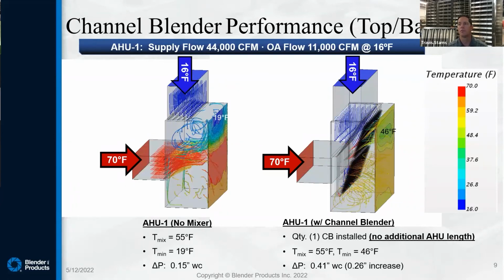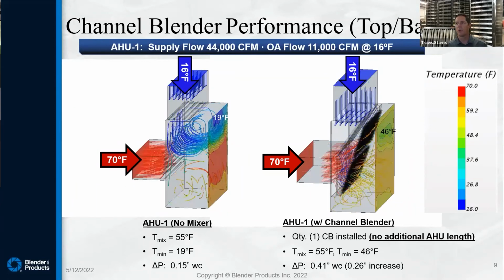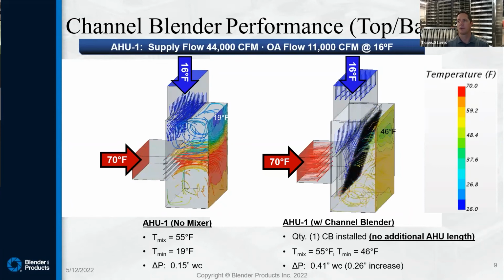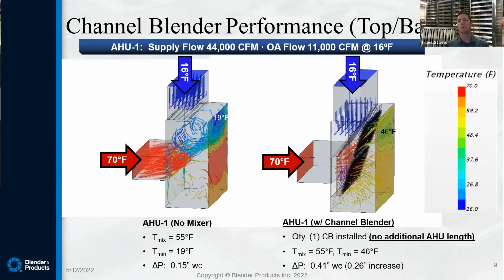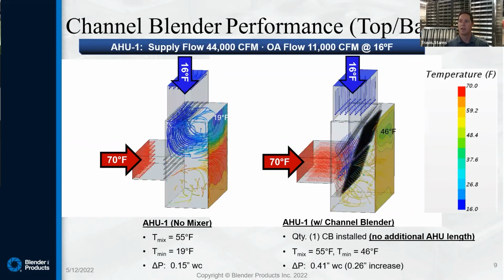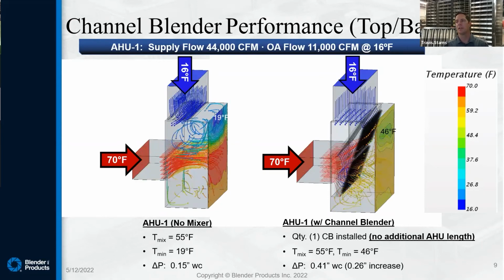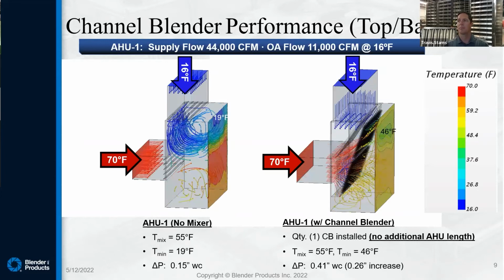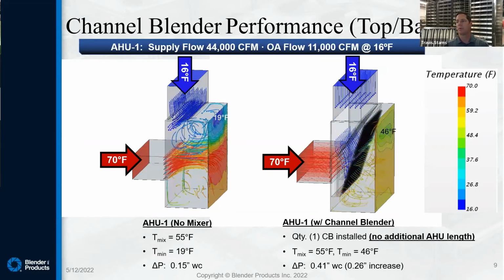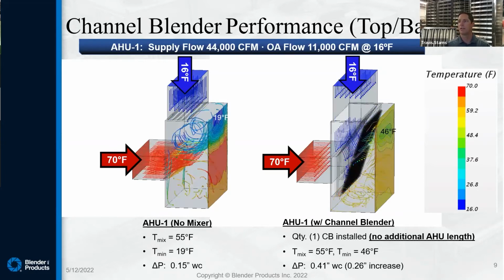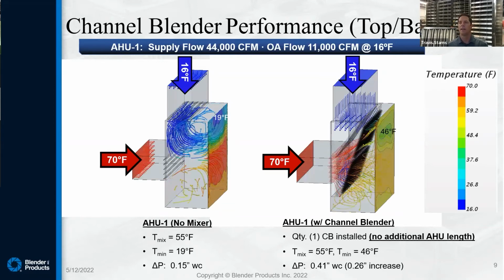And the same is true amongst the return air. So before those air streams come into contact with each other, we've taken measures to create uniformity inside that box. Then when those air streams and the proximity of those channel air streams come into contact with each other as they exit the damper blade assembly, now we promote heat transfer, and then you can see that gradient. It's a much smoother profile downstream.